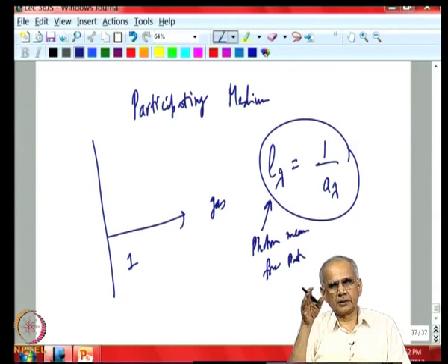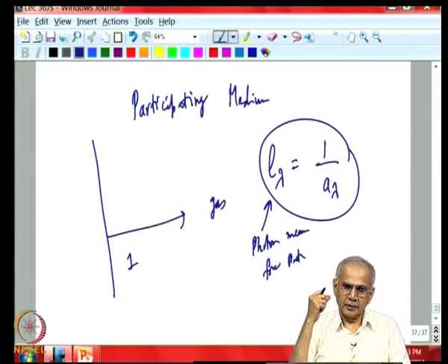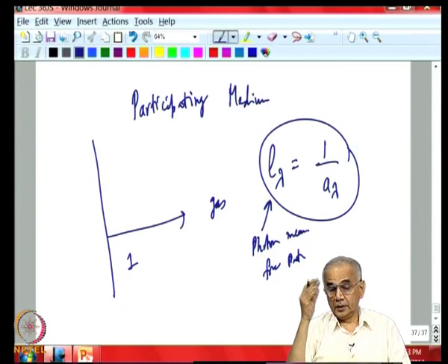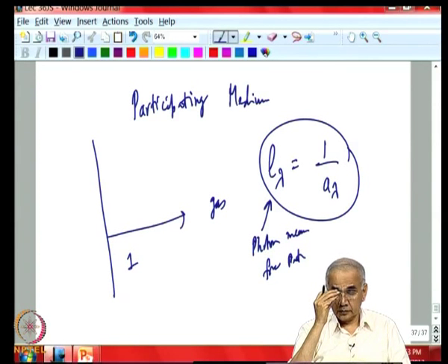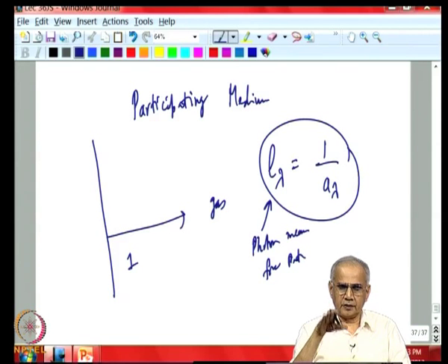So, once you know the distance, as the photon leaves the surface, you keep generating random numbers to decide whether that photon is indeed absorbed or is scattered. If absorbed, again the story is over. You just keep count of this energy being gained by that surface. That would conclude that photon's life. So, you go back and pick another photon.